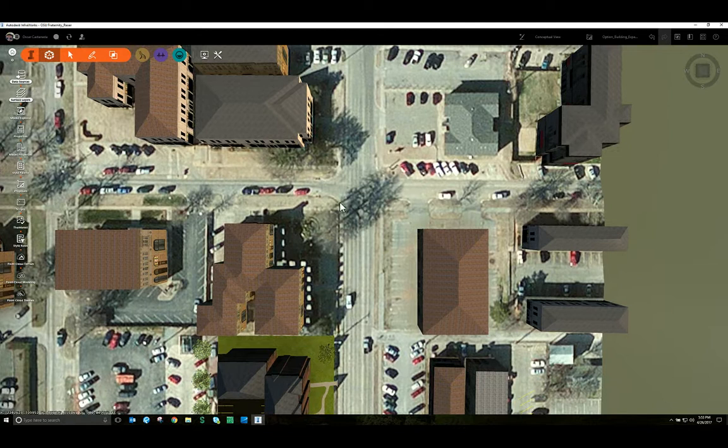So what we're going to do is a couple of things. The first one, we're going to use a polygon, an enclosed polygon 2D, which is the method that you said you used, but it's not working. All right, and that's going to be for the center line of this road. The next step, we're going to bring lines, just basic 2D lines from AutoCAD into Infraworks.